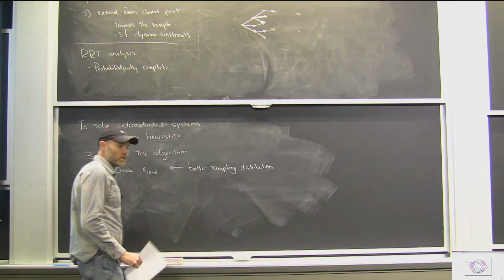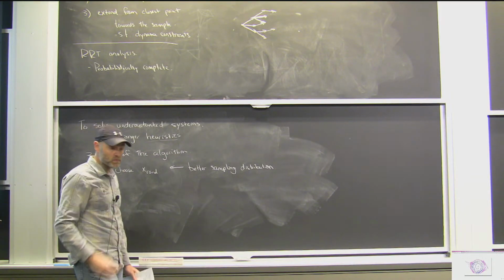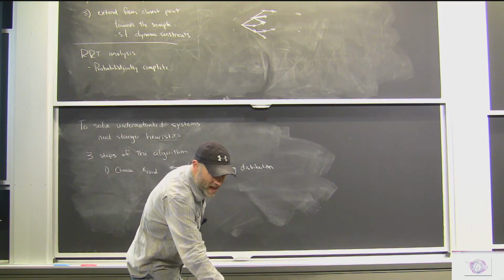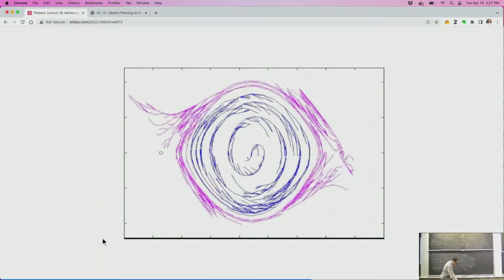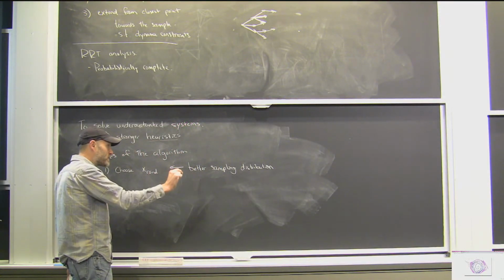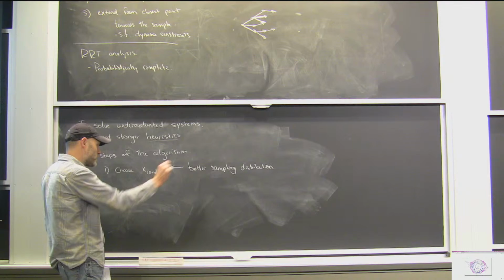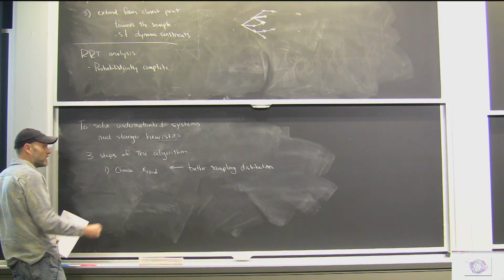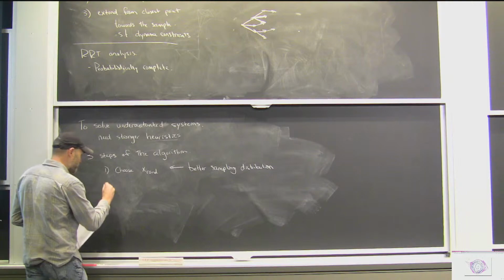Then we can potentially do better for a dynamical system. One of the things that feels obviously bad is that if I start sampling uniformly in the state space and my tree is only near the bottom of the pendulum, then those samples are just wasted samples. We're asking it to grow somewhere it has no chance of growing, so its best attempt is just not going to achieve the exploration that we hope for. If we could bring our sampling in to be more targeted sampling, on the path to the goal and maybe where it's capable of expanding, then we potentially stand to benefit quite a bit.